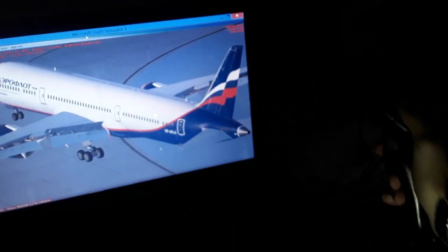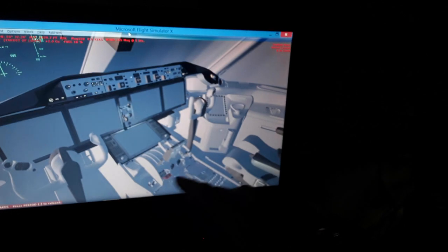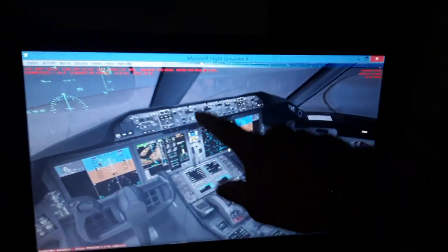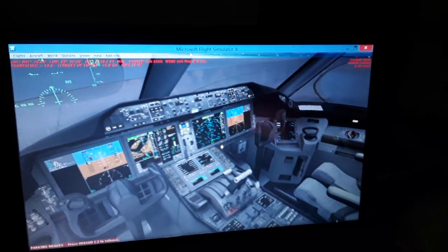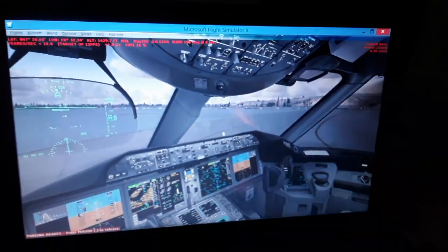We have the auto trim, the automatic trim channel, the horizontal tail stabilizer for the Boeing 787. So you can see the horizontal tail here when we move up and down. Also, we have the trim switch here to balance the aircraft in flight. So you use either the auto trim function over here, automatic trim from the autopilot flight director system panel.